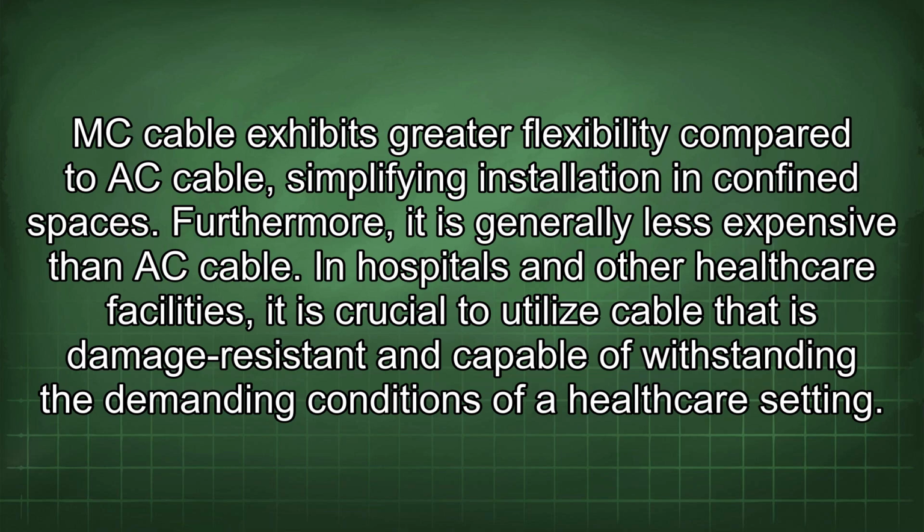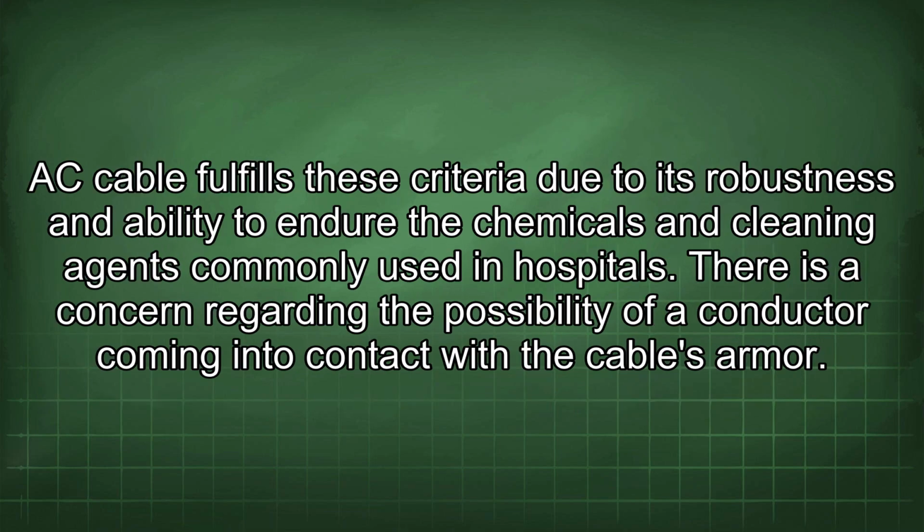In hospitals and other healthcare facilities, it is crucial to utilize cable that is damage resistant and capable of withstanding the demanding conditions of a healthcare setting. AC cable fulfills these criteria due to its robustness and ability to endure the chemicals and cleaning agents commonly used in hospitals. There is a concern regarding the possibility of a conductor coming into contact with the cable's armor.